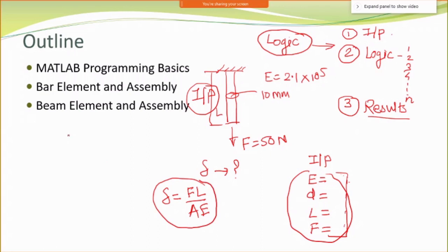This typically gives the deflection of the bar using a simple equation, that is Hooke's law. We can go back to Hooke's law and I will tell you what it means, and how we can derive this equation quite easily. We know the stress and the strain. One axis is strain, another axis is stress. I assume the slope of this is nothing but my E value, that is Young's modulus, and the line passes through the zero.